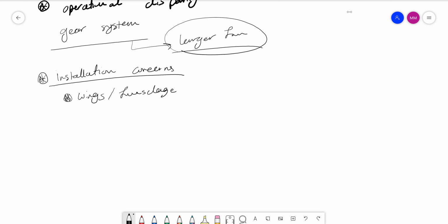You want to find the limit on the fan diameter you can have based on the designs of other parts of your engine. And also the nacelle weight here requires us to use composites, right? Because we want to reduce the weight as much as possible.